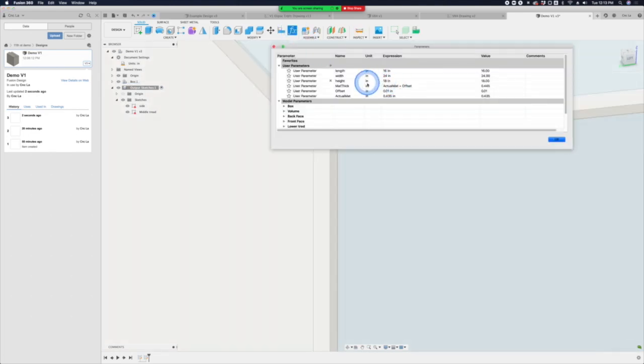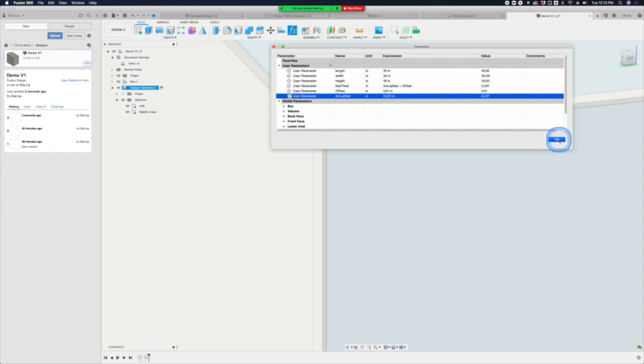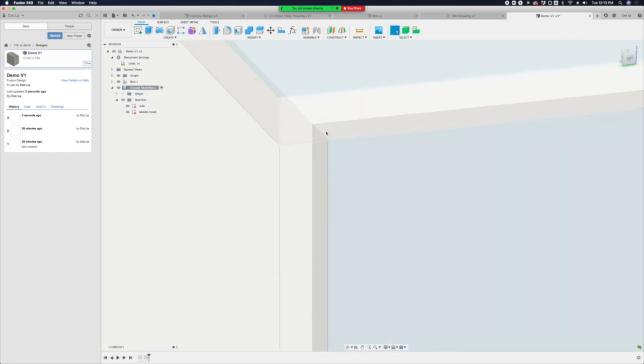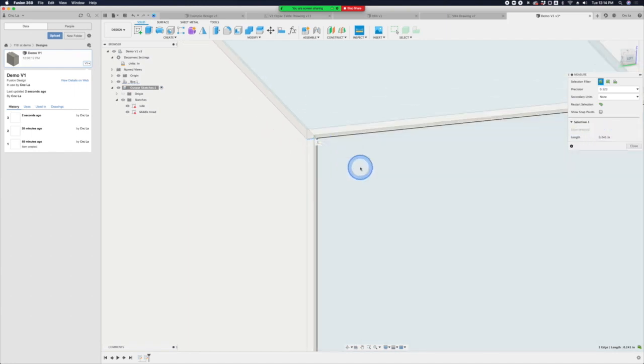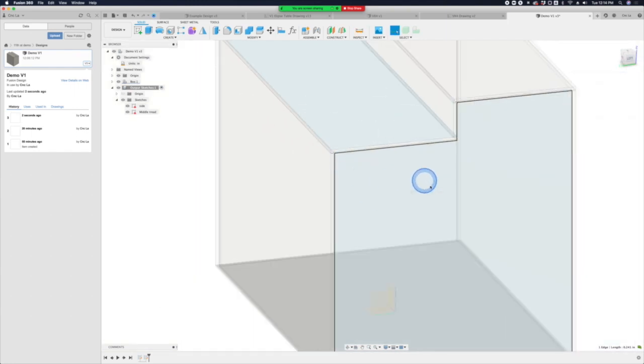And then just to make it a little more obvious, the actual material is going to be 0.231, but we still like that 10 thousandths offset. This is all now quarter inch, 231 plus 10 thousandths of an inch. So 241 here. And then this sketch, because it's referencing this geometry that's projected, is all changed.